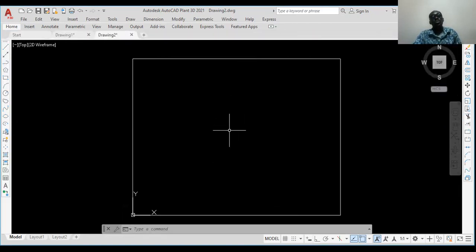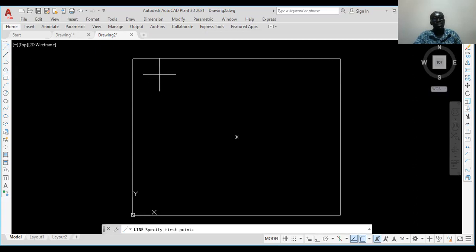Okay, so right now, to copy, how do we copy? We make use of the copy tool, and the copy tool can be used in various ways. When you want to copy what you've drawn, maybe an object. So quickly, we'll copy freestyle without dimensions. So I'll just draw a line now. Let me turn on auto mode to make the line straight, horizontal or vertical. So I draw a vertical line right now.